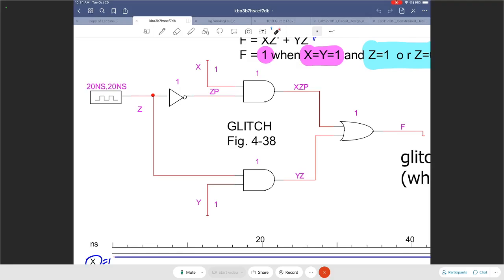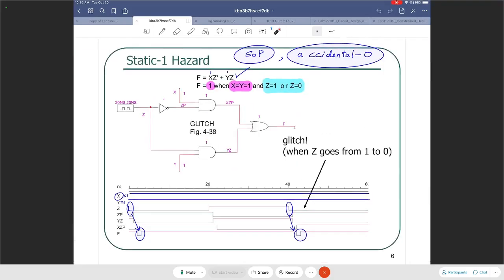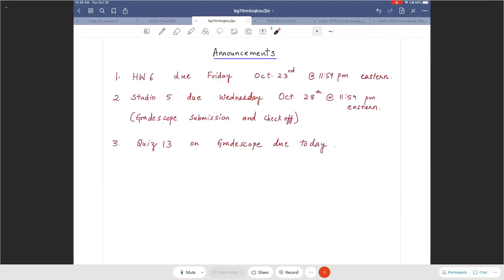Now coming to function hazard, it has to do with two or more inputs changing at the same time. When two or more inputs change at the same time, there will always be a possibility that a function hazard occurs. So you would answer function hazard may occur in that situation. So I hope that answers your question regarding identifying the type of hazard. Let us come back to the lecture for today.